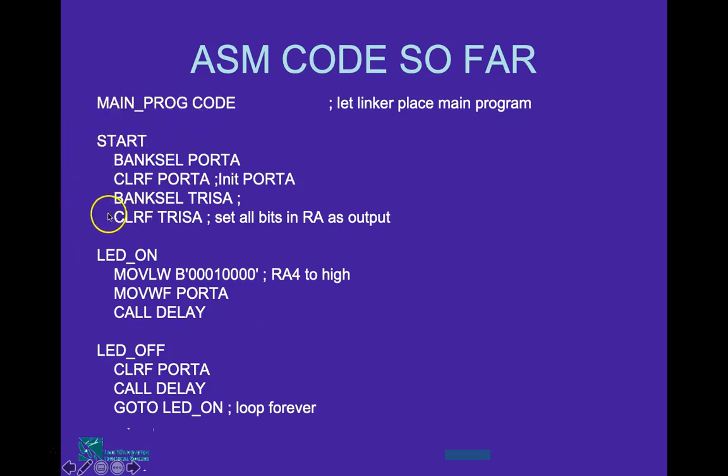We have used the start code, and then we have the LED on code, and then the LED off code. LED on instructions you already know, step by step, and you know that after turning on the LED, it will provide a delay, and then it will turn off the LED, and then again provide a delay, and after that particular time of delay it will go to LED on. So it will go to this instruction, and then we'll follow this loop, and then again go here. So you understand how to create a program on a microcontroller, and this language which we have used is assembly language. Now we are going to quickly see some of the instructions we have used for this program.